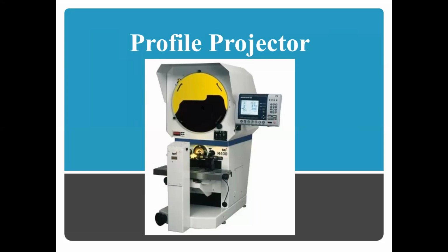Here, if you observe clearly, this is a screen, and here there is an operation keyboard and the digital inputs. In this case, one table is there. On the table, you place the work part which is to be tested. The table has two motions, in x direction and y direction, based on the movement of micrometers attached to the slides.